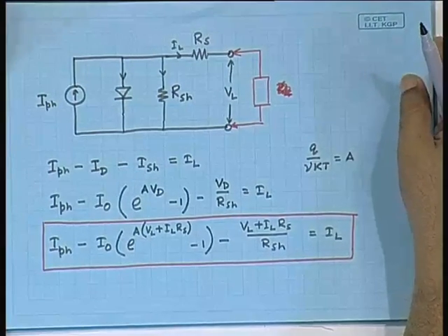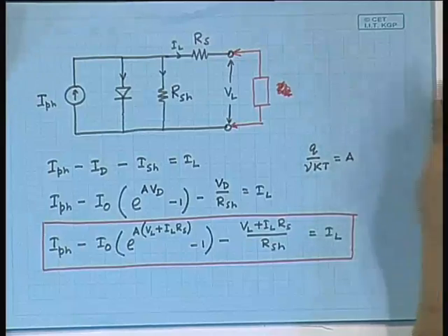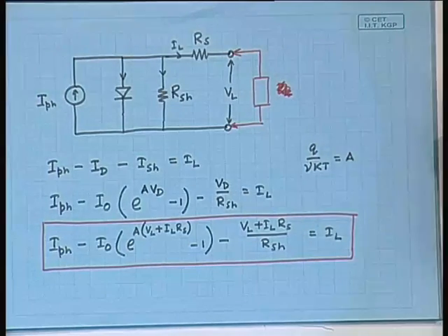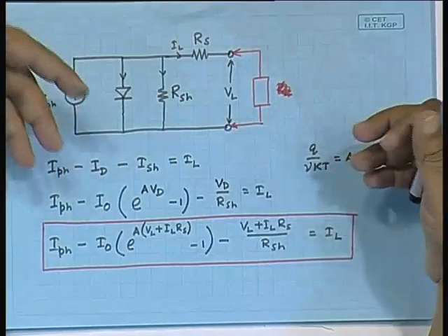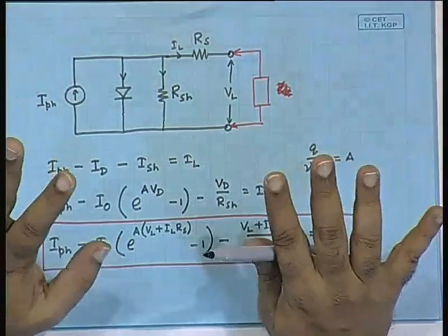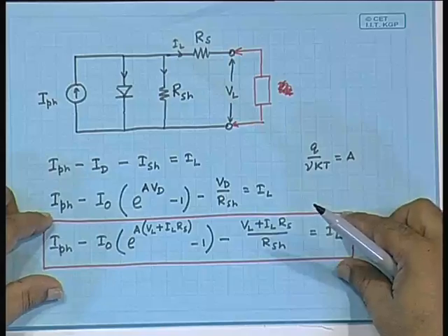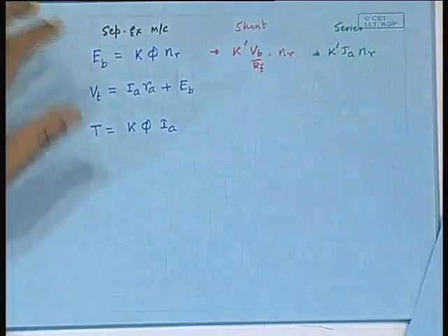An exercise that the energy engineering students will do at the final year level when you actually experiment with the machines, but remember that this is the basic idea, that this equation has to be linked with these equations to obtain the actual characteristics of the series, shunt and separately excited machines as fed from the photovoltaic panel. But in general you might take home the message that series machines perform better with photovoltaic panels than shunt machines.